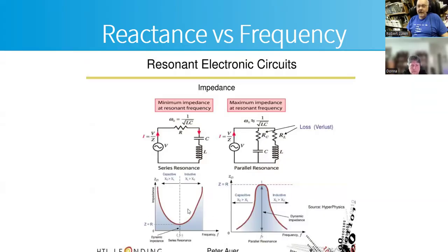The shape of this is going to be dependent on a bunch of things like parasitic capacitances, and the amount of resistance, which is going to affect the Q. The smaller the series resistance, the higher the Q, and it's going to be a much sharper curve, where it stays high, comes down to almost a point, and goes back up.